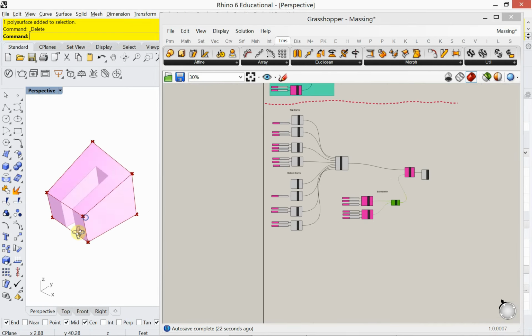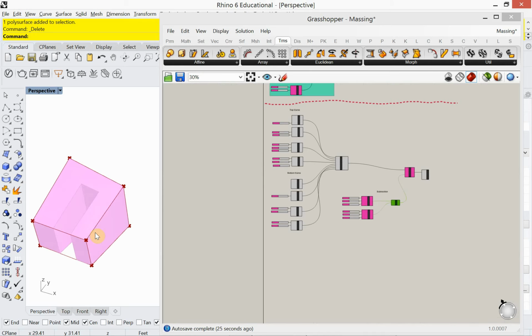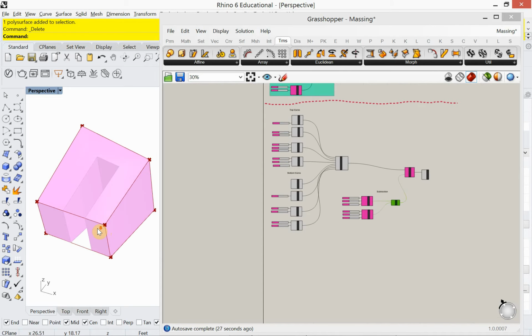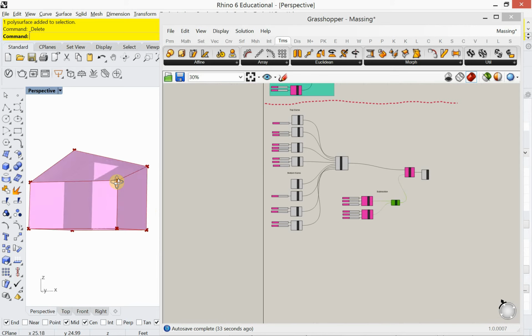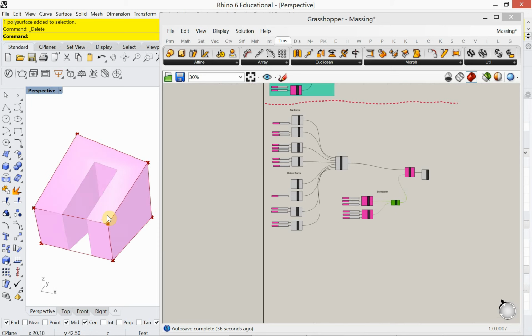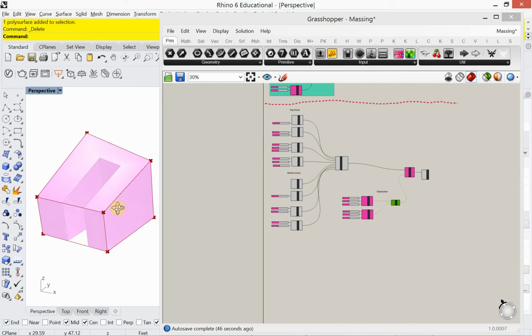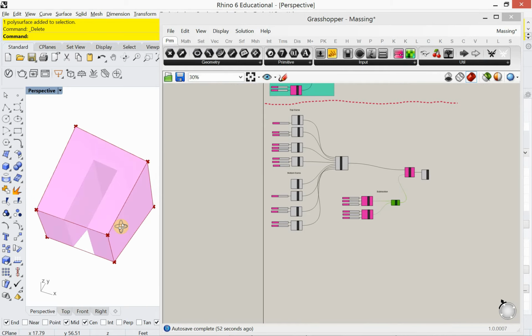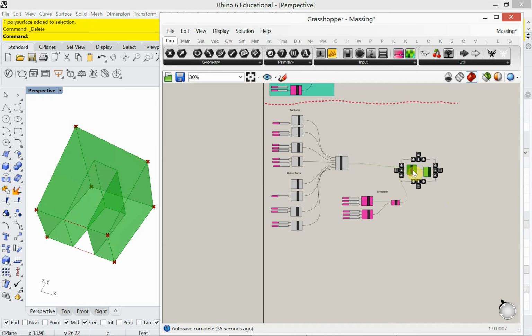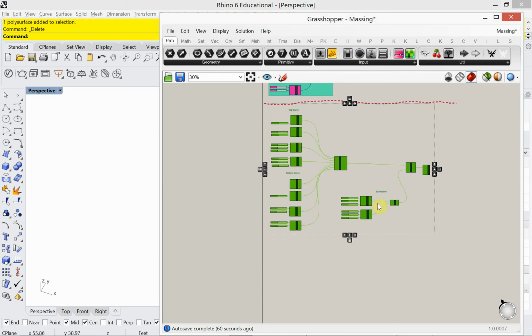Alright, so one last thing is just to talk about drawing techniques, because everything I've been doing right now has been rectilinear, so just kind of using straight curve segments. So you just want to keep in mind that you can draw lines and arcs, and you can draw curves in Grasshopper. So I just want to spend a little bit of time just drawing a polyline that just has a 3-point arc on it, just so that you can see that and give you some inspiration. So I'm going to select all of this, right click, and turn the preview off.